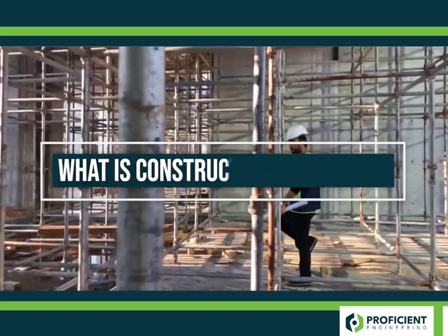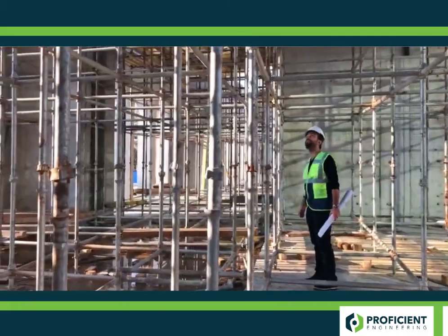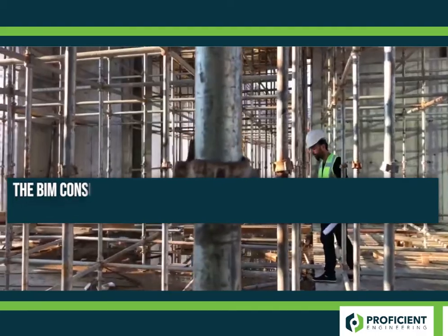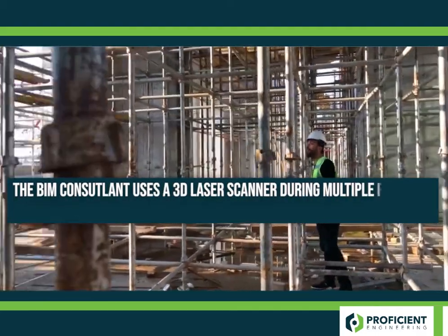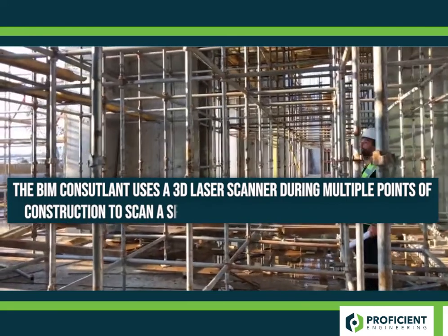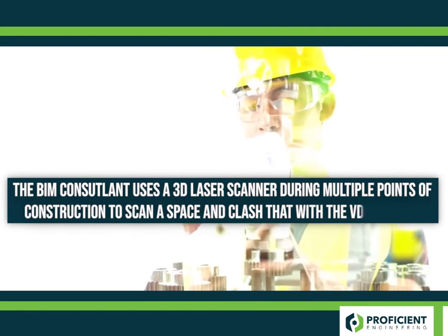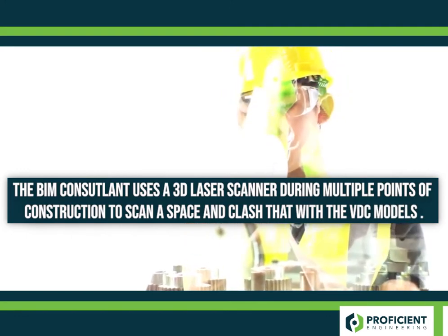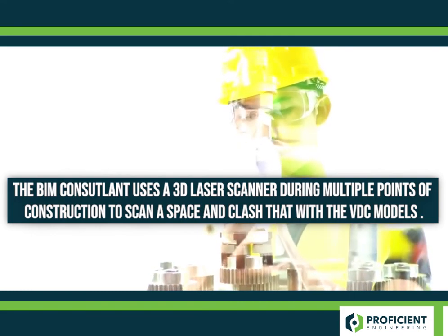What is construction validation? Construction validation is basically validating the construction process. So we can go in with a 3D laser scanner, multiple points during construction, scan the space, and clash that with the VDC models and see if the GCs and subs are coordinating as we designed.